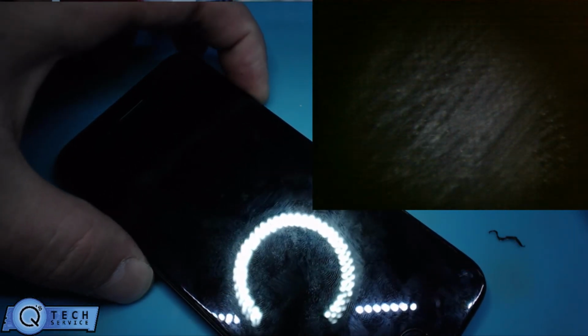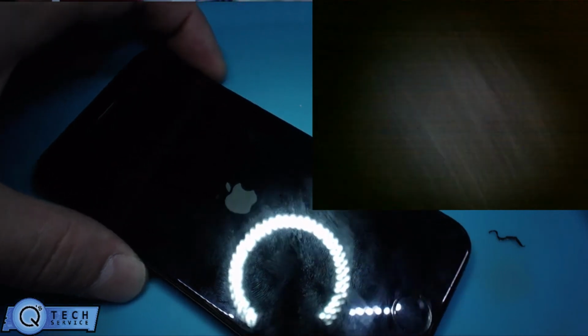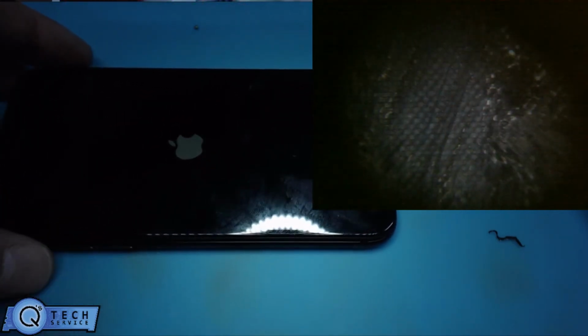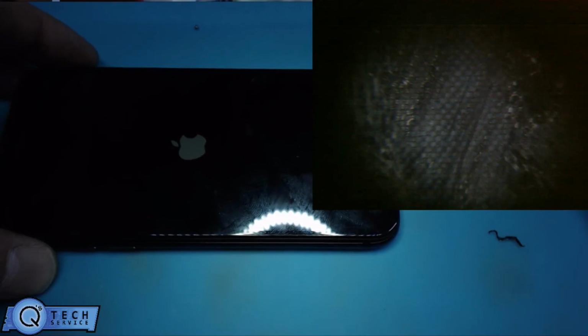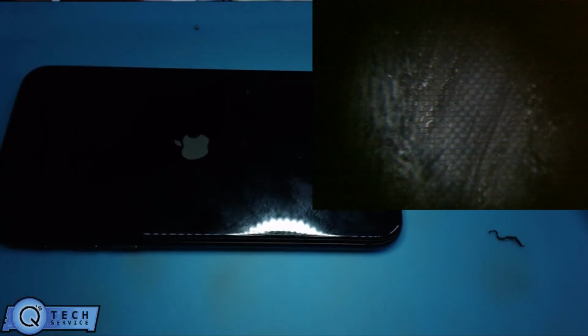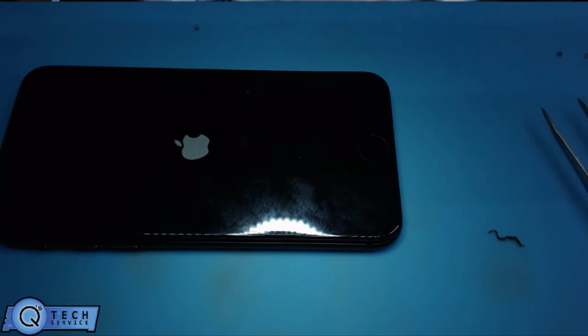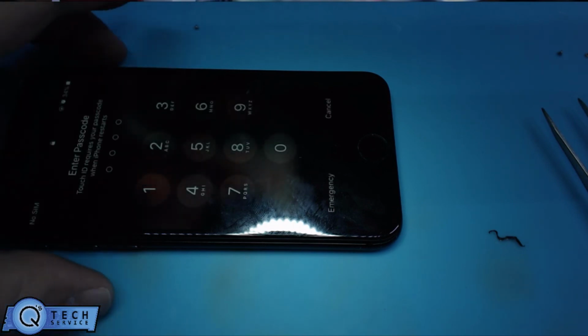Alright, so I'm powering it up. There we go. Remember, it took 5 minutes before. So that's another sign right there that you have audio. And you could see that we took the audio IC off, and when I was running the jumper wire and I just tapped the pad, it was basically just disconnected.